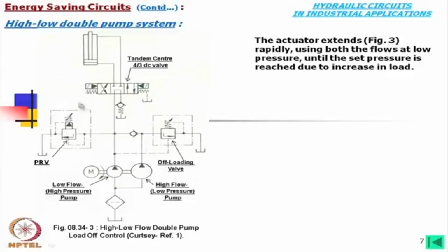And this is a pressure relief valve. This is for when the total system pressure, say 10 megapascal, exceeds 10 megapascal, then the oil will flow through this valve. Now, even if we omit this valve, and if we are sure the pressure is not exceeding 10 megapascal, then also this circuit will work. So, this is basically a safety valve. Now, how is it being operated?